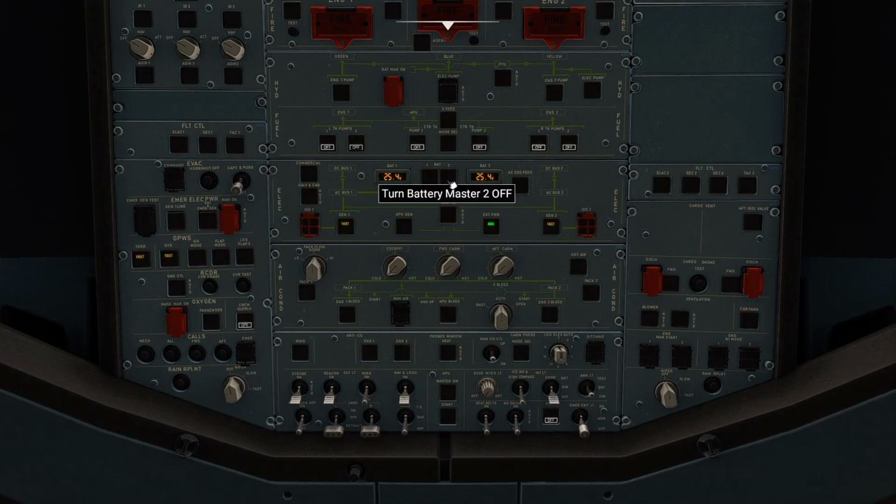Firstly, you will turn on battery number 1 and number 2, followed by the external power for powering the aircraft before our aircraft uses its own engines such as the main engine and APU. But we must make sure that external power is available. If it is not available, then we can directly turn on the APU.